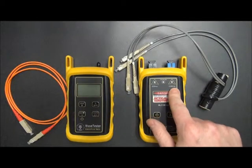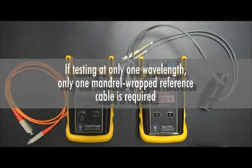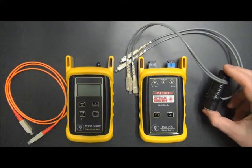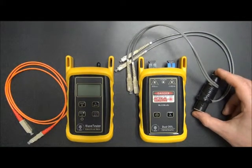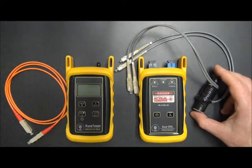since we're going to be doing a dual wavelength measurement. Now, if you're doing just 1 wavelength, you will need 1 mandrel wrapped cable, but because we're doing 2, I've taken a duplex cable and wrapped it around a single mandrel. It's a lot easier to handle 1 mandrel around a duplex cable than it is to handle 2 separate cables with 2 separate mandrels.